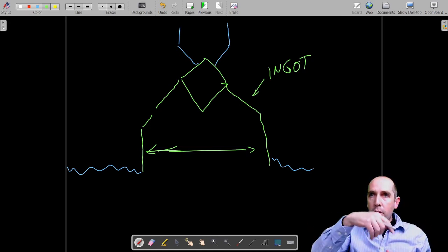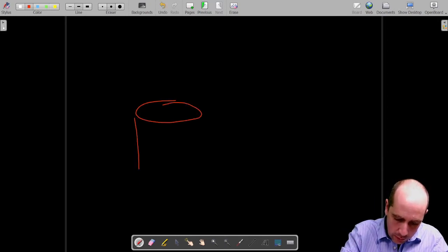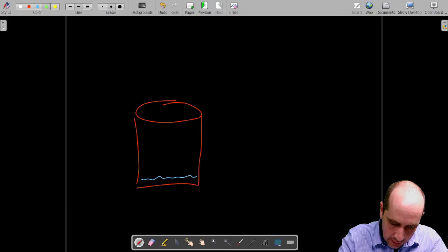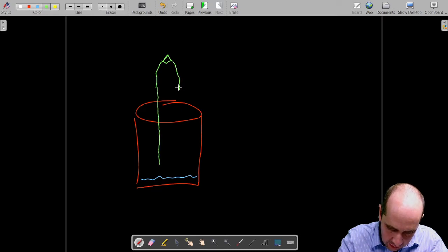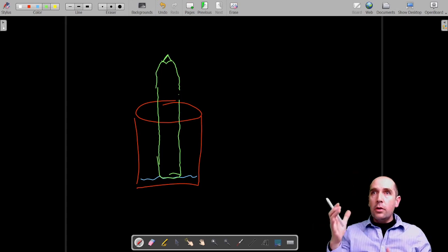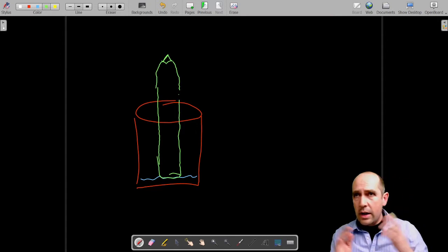So we can keep pulling and pulling, and eventually we will run out of material. So if we see this, we will have just very little material left, and the original seed will be something like that. And then we will have the ingot, which looks a little bit like a cylinder there, which is a large, very long single crystal of silicon. Okay, this process has variations around it.